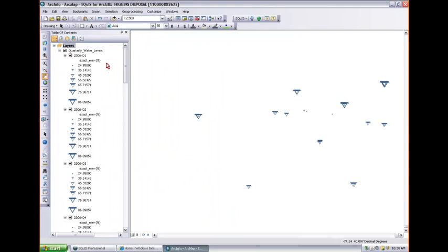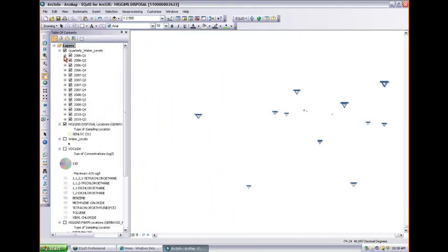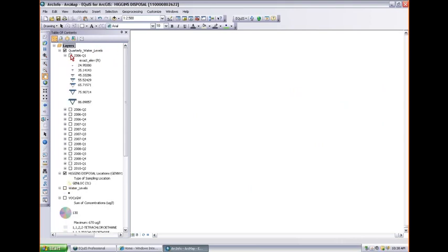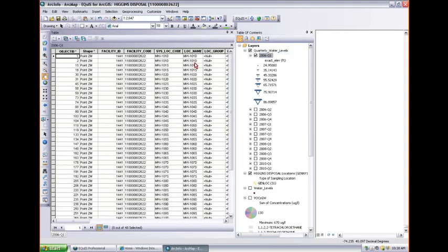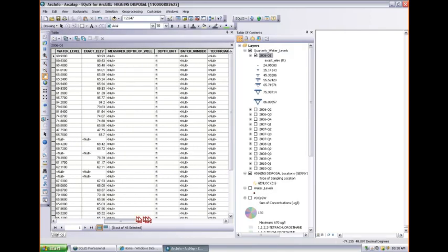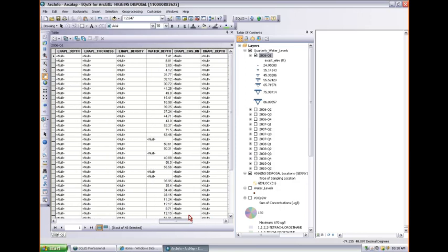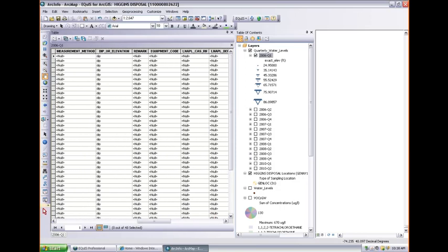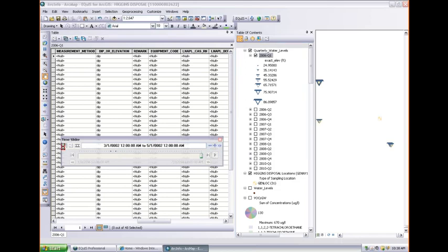We've got a trick when you're dealing with these group layers. If you hold down Control while you're doing anything, like I'm clicking this expand contract, it'll do it on all these sublayers. If I want to turn them all off and on, I hold down Control. So when we create a dozen or so layers, we've got no data here. This is quarter 1, 2006. Oh, because I have time on.